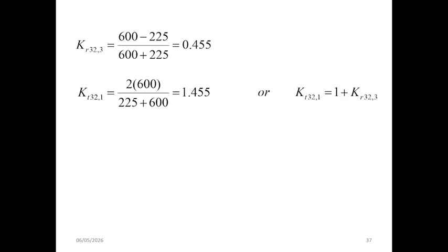A transmission coefficient greater than 1 does not violate physical laws. Instead, it reflects the fact that voltage can increase when a wave moves into a higher impedance medium, while current correspondingly decreases to conserve power.